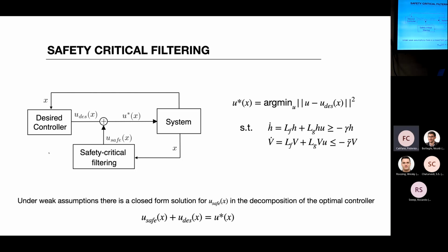Say, if you want to do only obstacle avoidance for a mechanical system, it turns out that the CBF is built to be a function only of the positional state of the system, because you want to do obstacle avoidance. So in the moment in which you calculate the H dot, exactly as Antonio said, the LGH is 0.